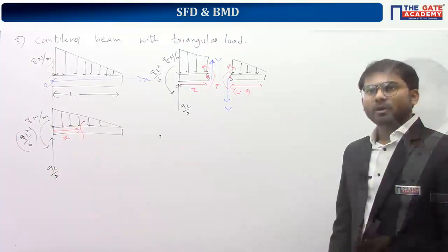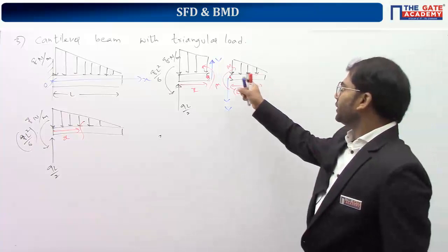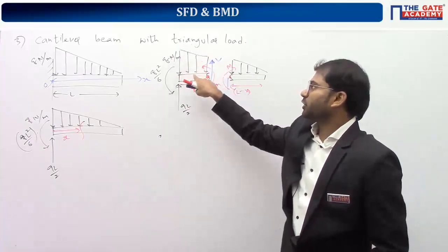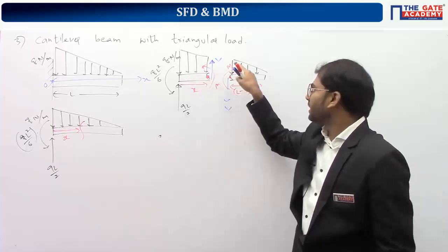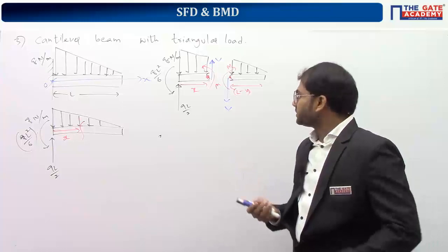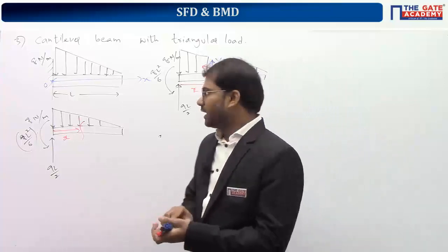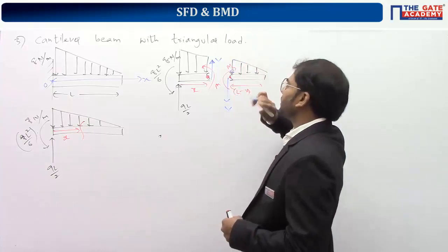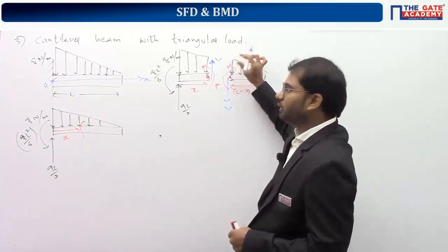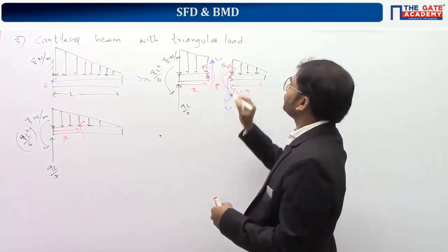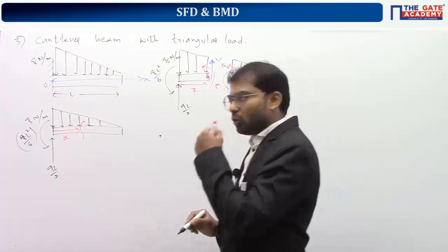What do you think? Obviously it is right side part, because we don't need to deal with this type of trapezoidal type of load or varying type of load. So here it becomes completely a triangular type of load itself. But here one problem is, we should know the value of this intensity. This is not equal to small q. Let's take this intensity as capital Q. We should get the value of capital Q. So how to get this capital Q?